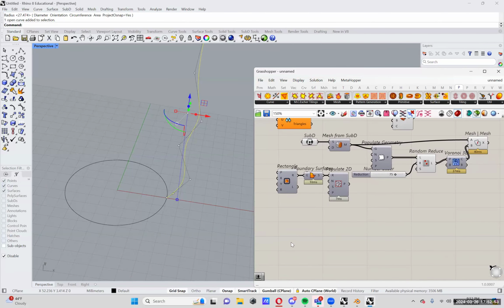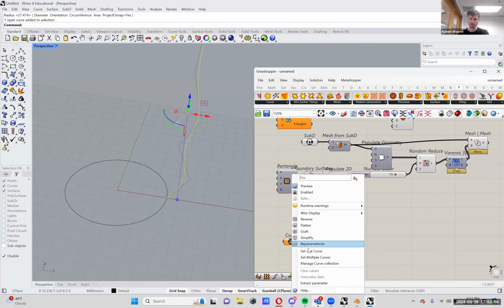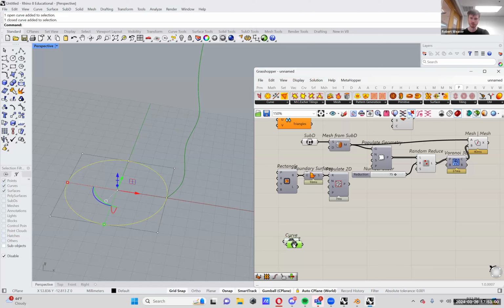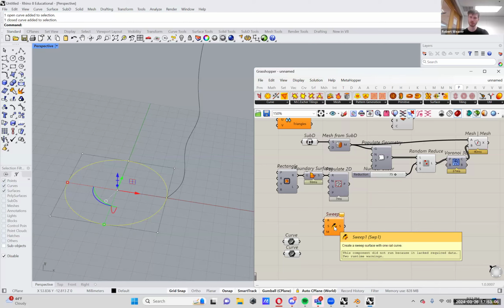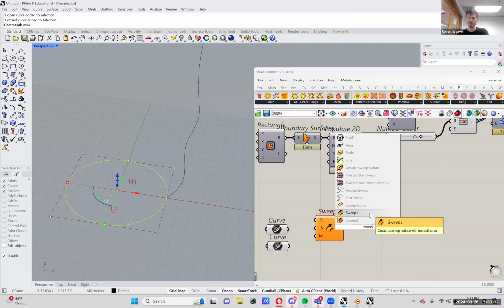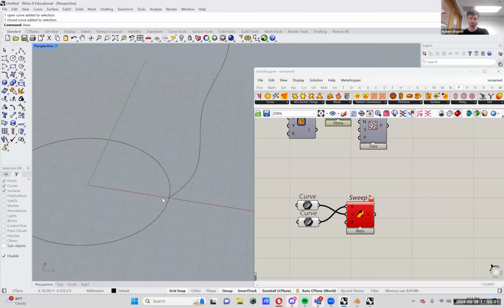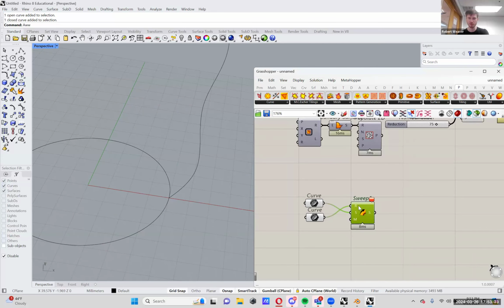You can do this in Rhino with Rhino commands, but we can also do it in Grasshopper, which is usually my go-to. And then we have the sweep commands. There are 2 sweep commands that you just saw there, sweep 1 and sweep 2. Right now we only have 1 rail curve, so we'll use the one that only wants one of them. We have the section, we have the rail, and this was doing this to me last week as well. It's very weird.